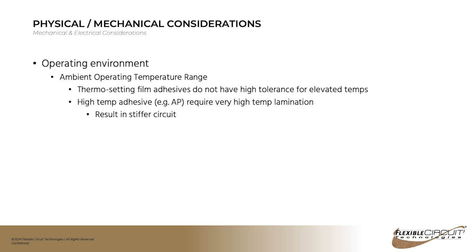And your operating environment, if you have high temperature requirements, typically the standard thermosetting adhesives we use are not great at higher temperatures. So you'll probably have to go with a different adhesive that laminates and operates at a much higher temperature. This is going to have a definite impact on the stiffness of the circuit because these adhesives are stiffer, and it's also going to have an impact on the overall cost and on your supplier base, because not every supplier has equipment that can laminate those high temp adhesives.